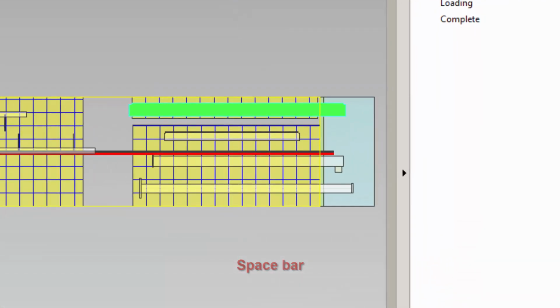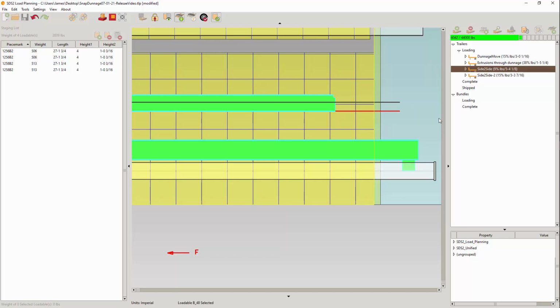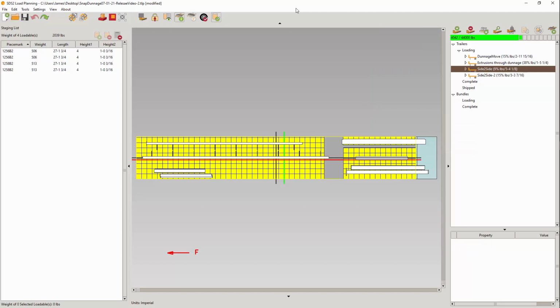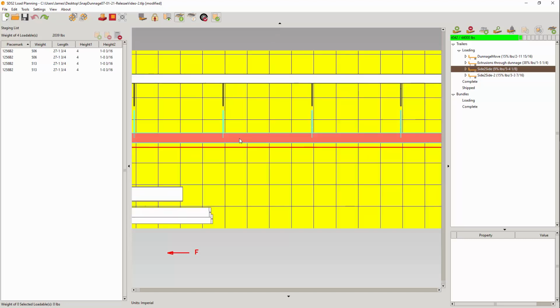When I select this loadable on a different dunnage and press spacebar, it does not snap to the loadable on the other dunnage layer. Notice, when I select these two and press spacebar to snap, the distance is maintained between the two selected loadables. Notice the extruded shear tab is nested inside the loadable from a previous improvement. You can also hold down the space bar while you are in the middle of a move, and you will see that as I move the selected loadable, the snapping routine is run.